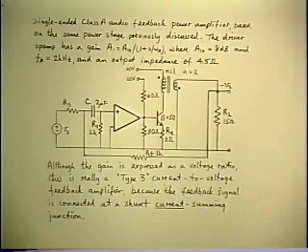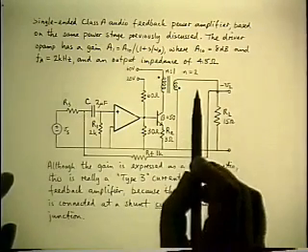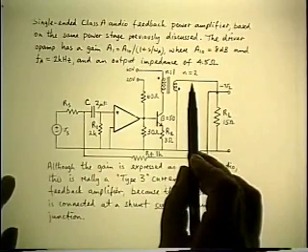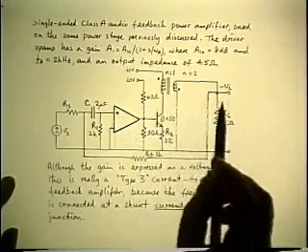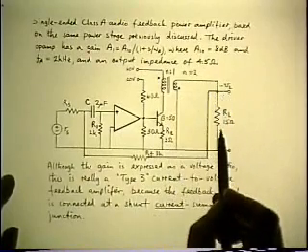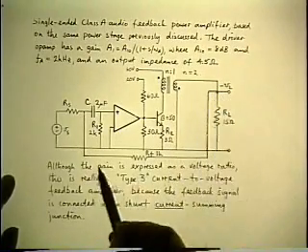So just as an example, let's go back to this audio amplifier that we'd had before, because this is a case where we chose to do current injection. And the point where we did the injection was at the secondary of the final output stage, because we'd modeled everything before that point into an equivalent current generator, and the only thing left externally was the load and the feedback path.